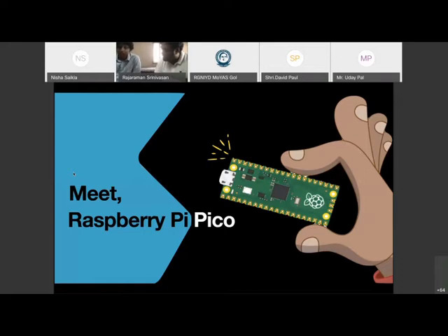Another feature of the Pico is that it offers UF2 bootable loaders in the ROM memory. So in the flash memory, if you drop any UF2 file, it will automatically pick it up and start reading it and installing everything that you need. So you don't need to go through the hassle of installing something and breaking our head too much with things.